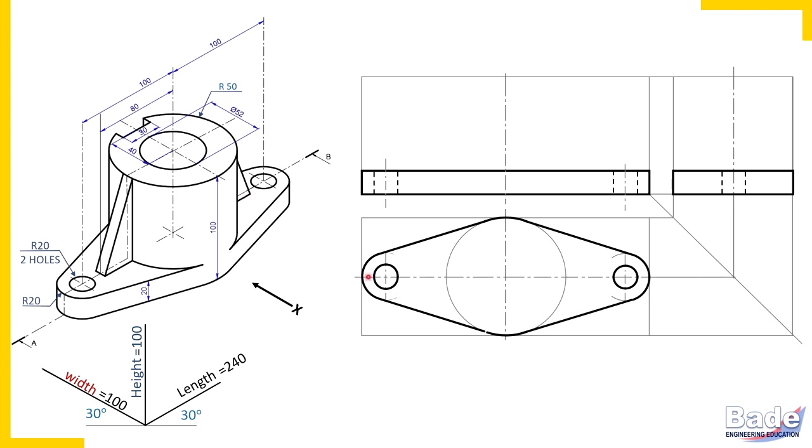Okay, now let's proceed for the cylinder. Two concentric circles because it's a hollow cylinder. Just check the corresponding radius and draw these two concentric circles. Cylinders appear as a rectangle in other views. In one view a circle, remaining two views rectangle. Simple. It's a vertical cylinder, therefore in the top view it's a circle, remaining two views rectangle. So draw end projectors and complete the cylinder. Height of the cylinder is, from base it is given 100 millimeters. So of course up to the top.